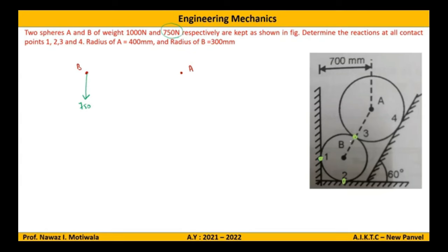So because there are 3 contact points, there will be 3 contact reactions. अब रिएक्शन देखते आएंगे कैसे. अब तो तुम मास्टर हो गए इसमें. पॉइंट 1, the surface is vertical, तो रिएक्शन कैसे आएगा? Horizontal, from surface to the body. So I will name this as R1. बराबर है? Yes, sir. Regarding R2, the surface is horizontal, so reaction will be vertical. And from surface to body, that means my reaction will be like this. This is my R2. किसी को doubt?